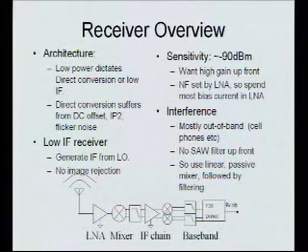Okay, so from a power point of view, basically we're stuck with either direct conversion or low IF, because anything else involves a high IF, and high IF means high frequency, which means power. So that's no good.